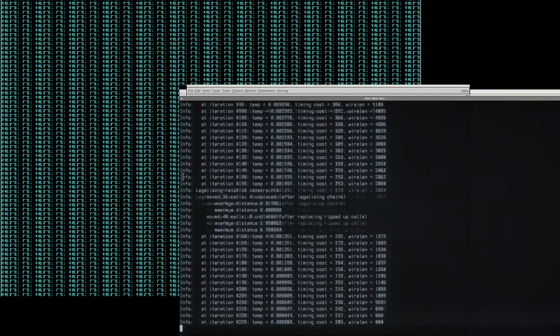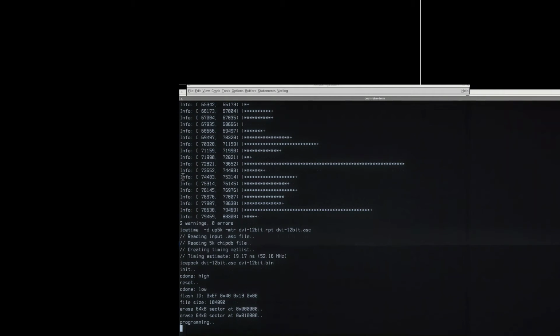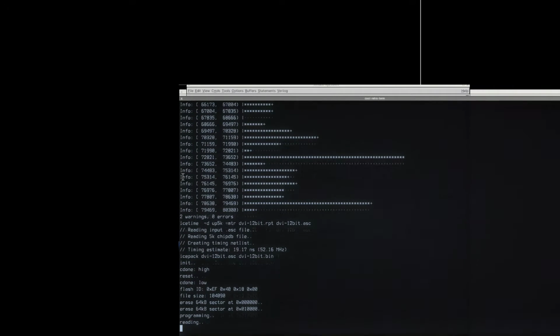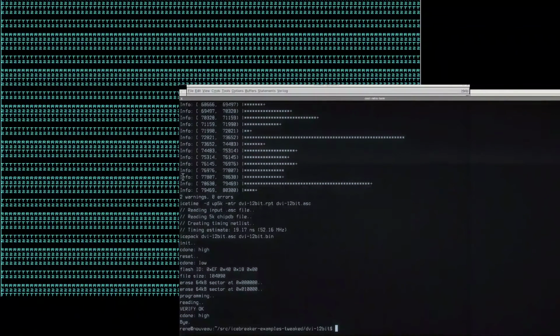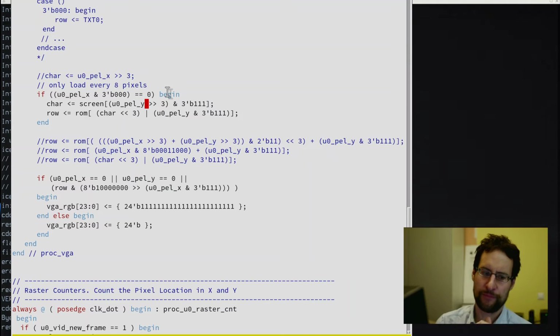Because this is a relatively high frequency signal, the pixel clock is quite some megahertz. And maybe the example that I based upon is already not perfect, and maybe this is also why it's off by 1 from the original example. Computing the signal propagation time of these wires and logic elements takes too long for the pixel clock, and maybe this is why this is slightly garbled.